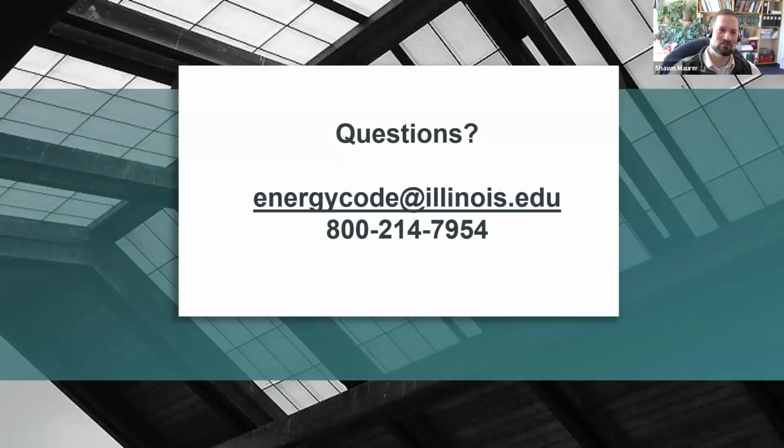So if you're enclosing a porch and it's still thermally isolated from the house, you don't have a permanent opening with an unweather stripped, uninsulated door where you have free communication of air between the conditioned space and that porch that would then indirectly condition the porch, or you don't have a direct conditioning like a duct extension or a supplemental heating and cooling unit on that porch, then it does not need to meet those thermal envelope requirements in the code.